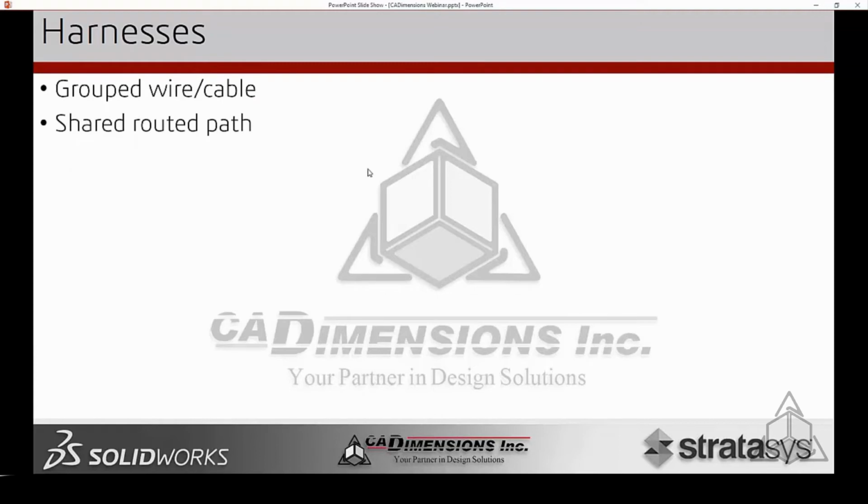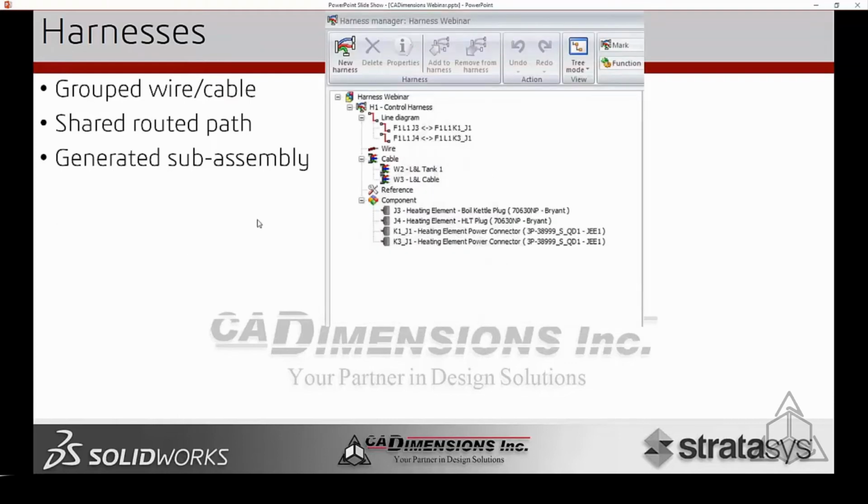We don't want to harness something if there are 2 items that are going to go opposite directions. We want to make sure that they're going to be bundled together to their endpoint. A harness works slightly different than a wire. The wire becomes its own part inside an assembly. A harness and a cable actually generate their own sub-assembly inside of our project.